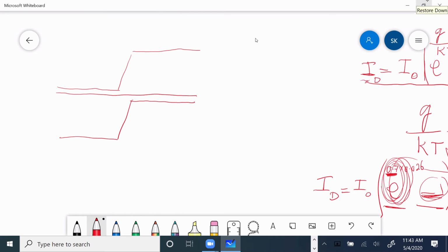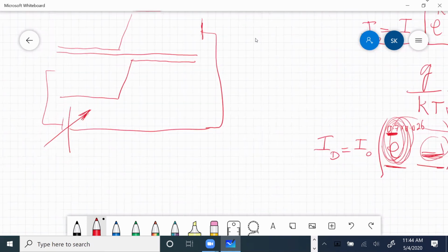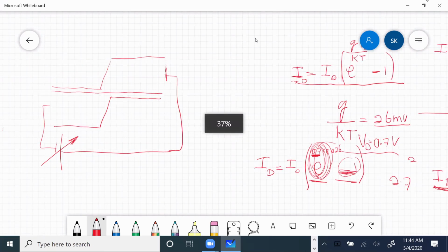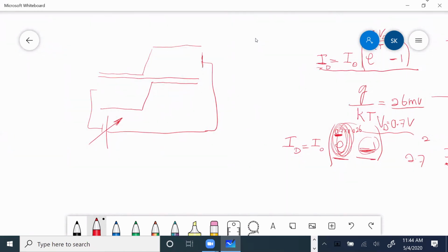Now we are applying a battery, connecting the n-type and the p-type, so we're applying voltage, n to n-type and p to p-type. What happens to the energy band diagram? In fact, the Fermi level breaks up.